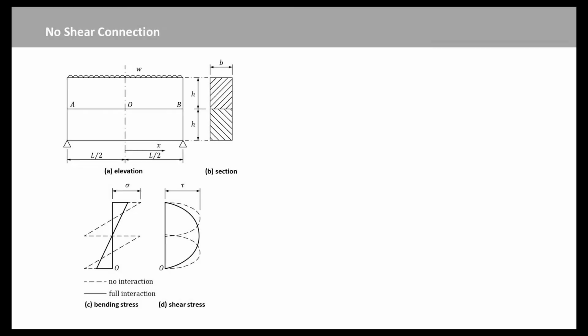Next, we will introduce the full connection using a simply supported beam of rectangular cross-section. Beams whose strength depended on shear connection between parallel timbers were used in medieval times, and survive today in the form of glued laminated construction. Such a beam, made from two members of the same cross-section as shown in Figure B, will now be studied.